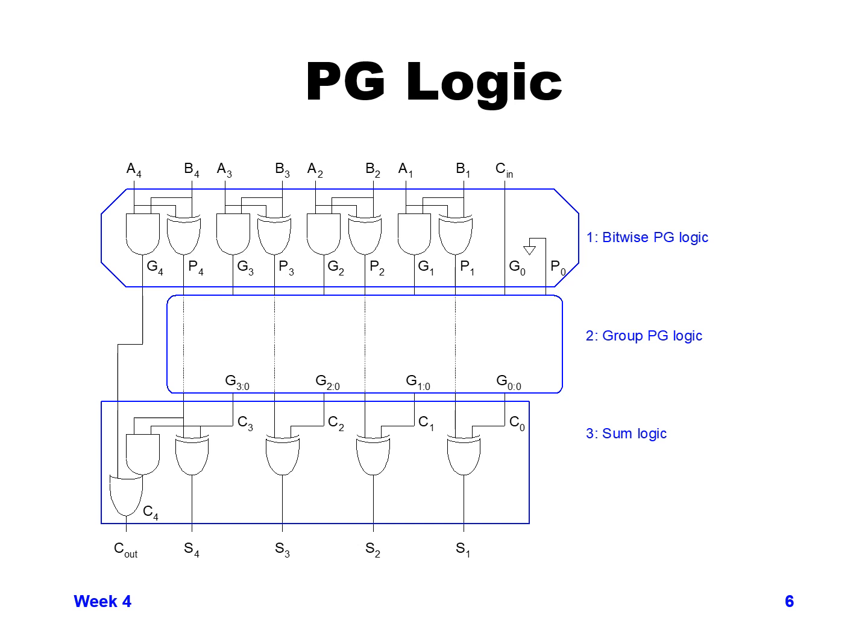So with just one stage delay, your propagate and generate for every single bit can all be done, and propagate 1 and generate 1 all the way through propagate 4 and generate 4 are all calculated and sitting there waiting for the carry logic to go through this row called group PG logic.